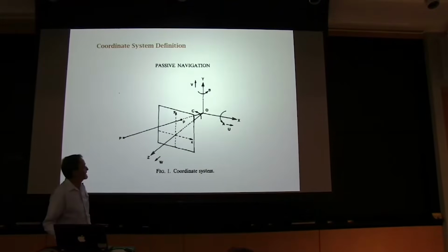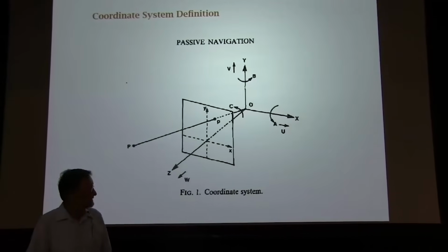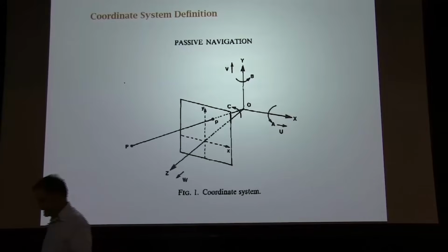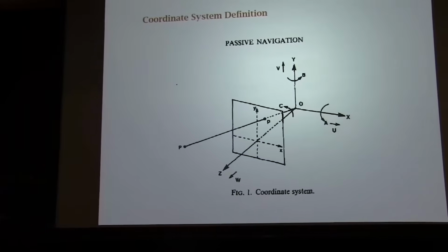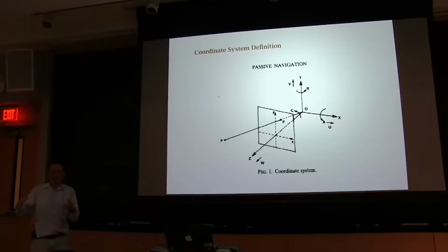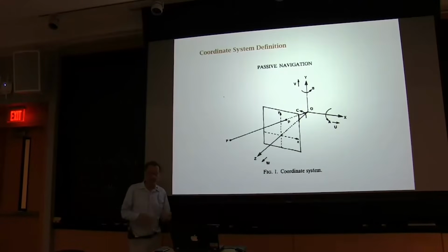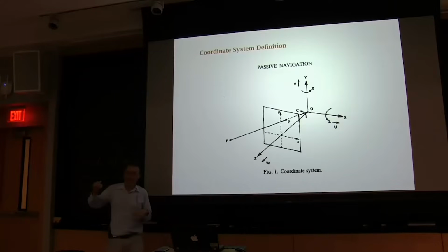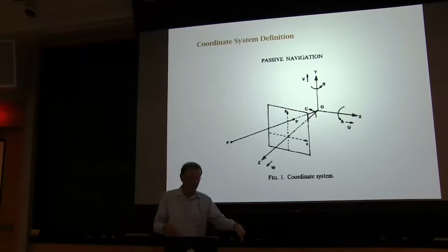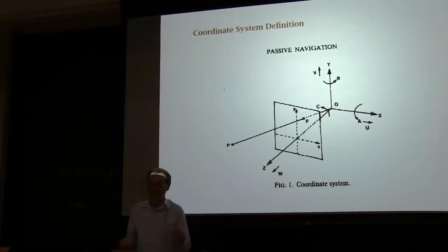So we'll be talking a little bit about coordinate systems and transformations between coordinate systems. For example, in the case of robot applications, we'll want a transformation between a coordinate system that's native to the camera and a coordinate system in which the robot has kinematics programmed into it, so that you can tell it in X, Y, Z where to go and in angle how to orient the gripper. But that's in terms of its defined coordinate system, which is probably, the origin is in the base where it's bolted to the ground.